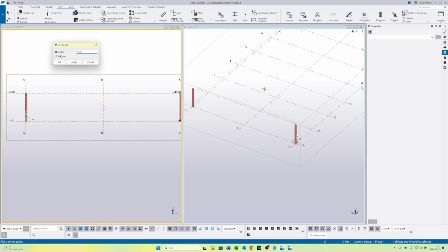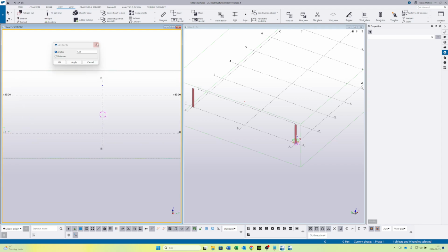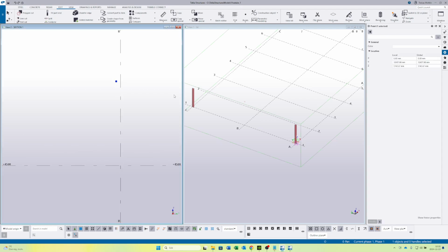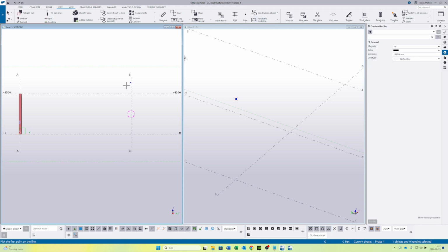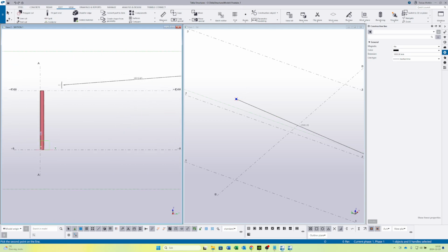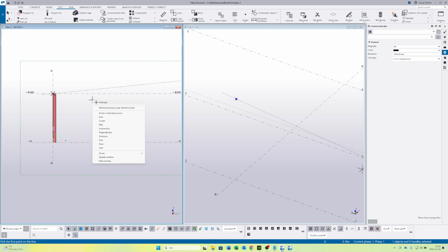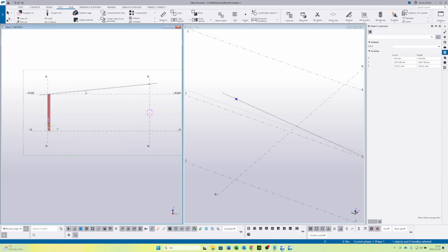And in Sweden, it's quite common that the lowest possible slope is 5.7 degrees for metal roofing. So I'm gonna apply that, and then I'm gonna go from this point to this point. Then interrupt the command and close. So as you can see now, it placed a helping point here. And this is in both the 2D space and the 3D space. So if I model out a helping line, I can snap to this point, and then I'll snap to my corner over here. Now I have a line that I can place my rafter on.